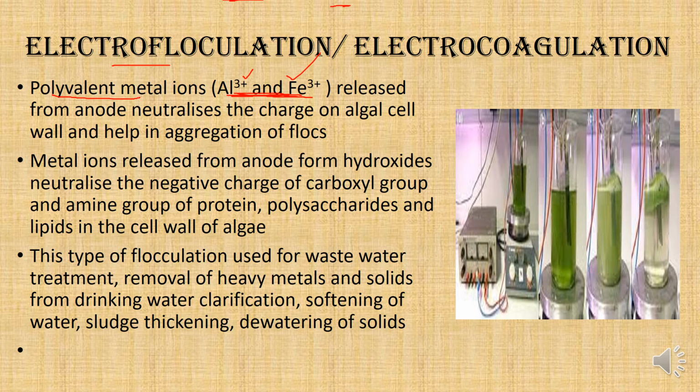But one added advantage is that in this electrolysis, or electroflocculation, electrocoagulation, the water is also converted into oxygen and hydrogen bubbles, and these bubbles bring the algae to the surface. The algae bind to the surface of the bubble. Say, for example, this is the hydrogen bubble, and we have all the algal flocks surrounding it.